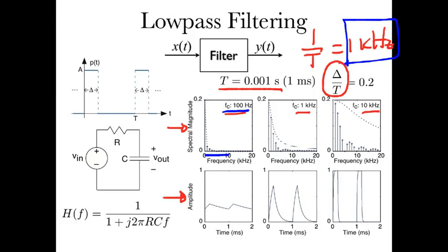And you get a somewhat lumpy looking output. It's not even clear that there were pulses in there originally. It's really low-pass filtered. So low-pass filtering tends to produce signals that don't vary very much in time. They can't wiggle very quickly because the higher frequencies have been suppressed by the filter. They're low-pass, remember. They tend to attenuate high frequencies.